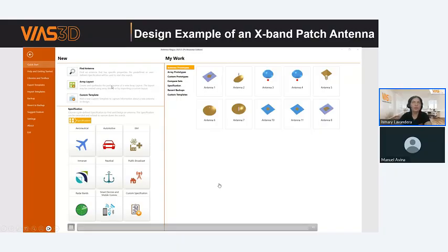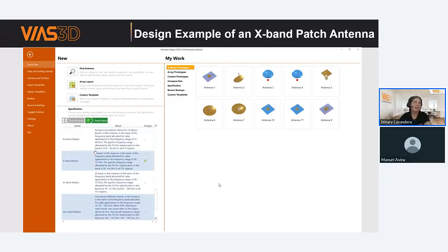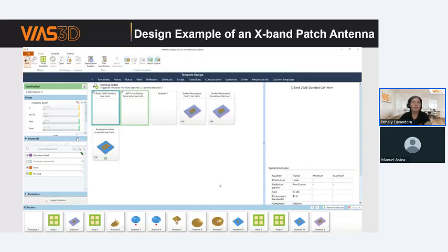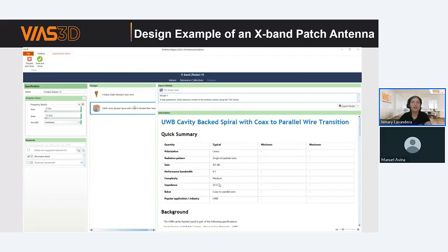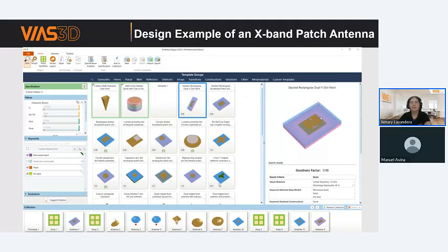So as you can see, you will see the GUI directly when you open Antenna Magus. Then you go to the specification for radar, and then select the X-band radar, which we have there. So once you click there, it will show up the complete GUI with all information. As you can see, the values for the X-band and the keywords used for X-band. And these two that you see here are the specification-based design examples, which we cannot modify too much. And since the objective is to show you how the models could be, let us start from designing.